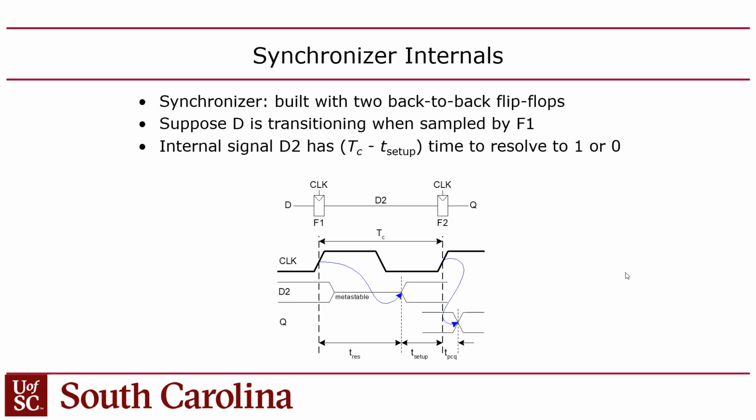Okay, so then what you can do is you could create a synchronizer. A synchronizer is where if you have an input, you add an additional flip-flop. So you take the input, like say from your buttons or your network cable or whatever, you plug those into a flip-flop, and then the output of that flip-flop gets fed into your real flip-flop. So basically what you're doing is you're protecting this flip-flop with an additional redundant flip-flop connected as a shift register, sort of, right? Two flip-flops connected in series.